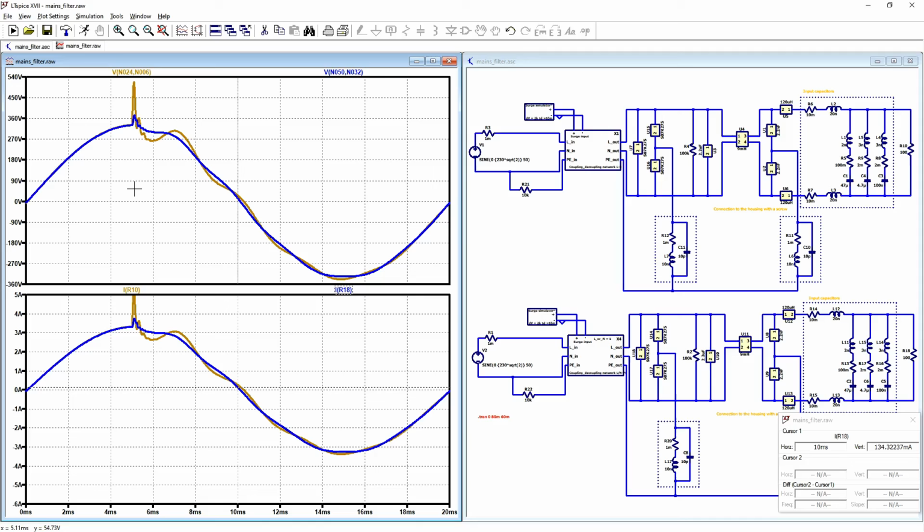Our voltage from the surge was 2 kilovolts. Now for differential mode it is 500 volts, and for common mode it is less. 500 volts with a sine wave above 300 at peak, it's pretty low. The total energy of this pulse is not so high anymore, and this is due to the currents. And you can check which component is taking which part of the surge.